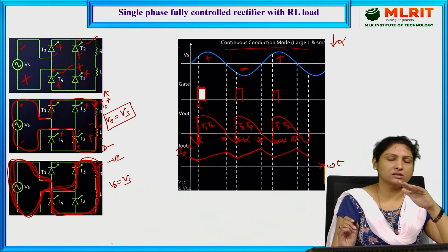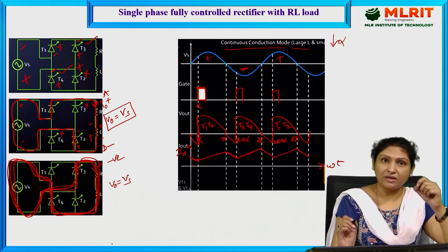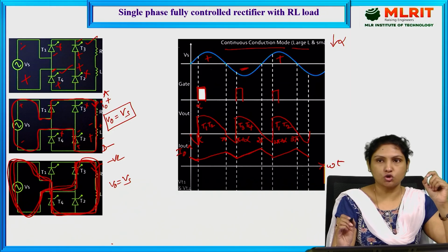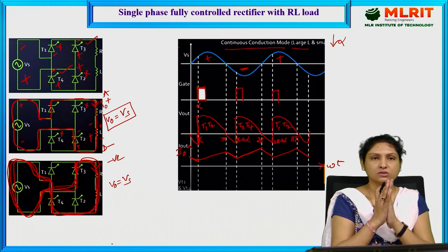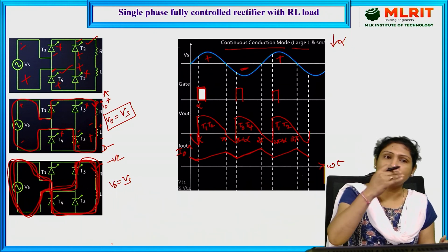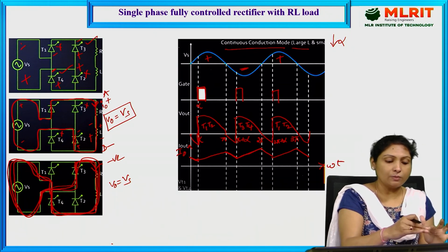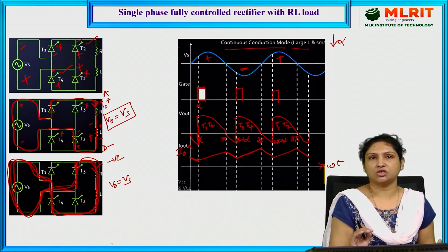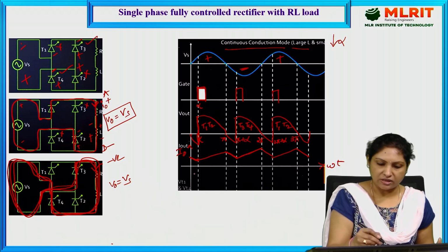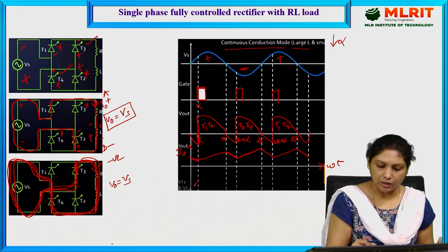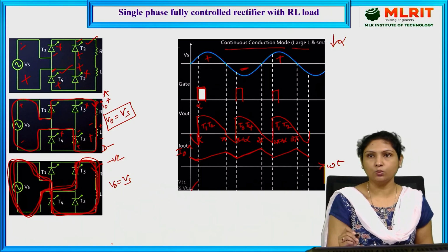We will almost consider it as, it will be very less. Since the on-state voltage drop across the thyristor will be very less, it will be almost considered as 0. And whenever the thyristor is off, at that instant, whatever supply voltage we are applying will appear across the switch. So that is the reason during the off condition, the supply voltage will be, as it is, applied across the thyristor 1 and 2.